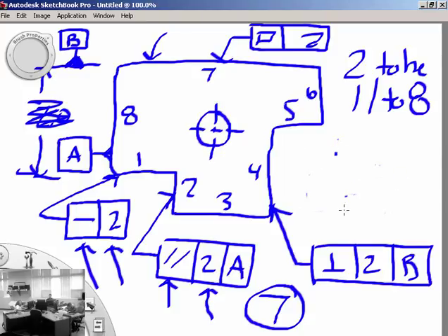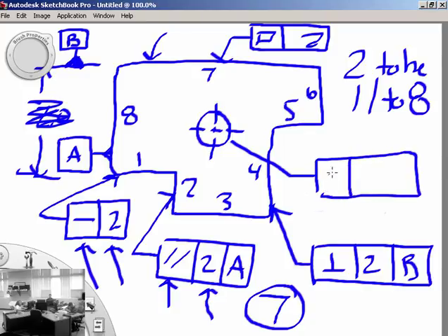So they are going to do maybe a feature control frame with this symbol, and then 2. So far, do you agree or disagree? Disagree. Why? It needs a diameter symbol, doesn't it? Because your zone for true position is typically going to be a round zone.